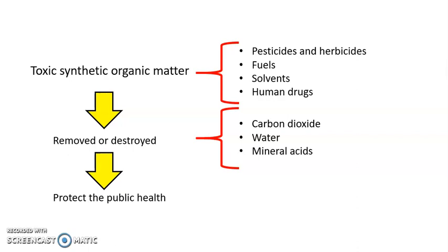So we have the contaminant residual present on the adsorbent. So we need to do another treatment for recovery of the adsorbent or something else for disposal of the contaminant. But advanced oxidation process has advantages over them because it can completely oxidize the synthetic organic matter to carbon dioxide, water, and mineral acids. So no further treatment is required in these cases.